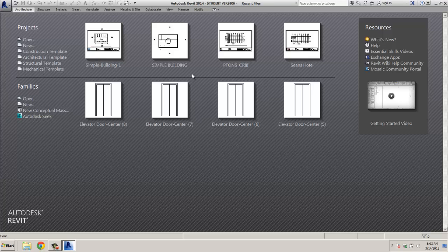If you look on page 1-4 of your textbook, Autodesk Revit Architecture 2014 Fundamentals, you'll see a workflow. And we can compare how we used to do things in regular Autodesk or AutoCAD software. We would model things in 2D, then maybe create a three-dimensional model, and then maybe create the sections and elevations all separately to create the construction documents. With the Revit software, we're actually building a three-dimensional model, and we can change things in any of our views. We can look at a plan view, change a door location or a window location. We can look at an elevation and change the height of a window location or the height of a floor elevation. And basically, when we make those changes in any one of those views, it automatically updates any of the other documents that are included in the model.